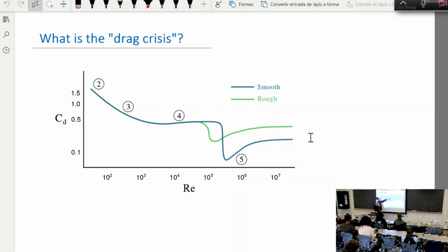It's the flow separation, right? The flow separation contributes to most of the drag, so that's why it is constant. And suddenly, at some point, the boundary layer becomes turbulent, more resistant to separation, and the separation shrinks. So you get a sudden drop in the drag coefficient. And then, as Reynolds number further increases, the turbulent boundary layer also has less viscosity, and the separation widens. You get higher drag.